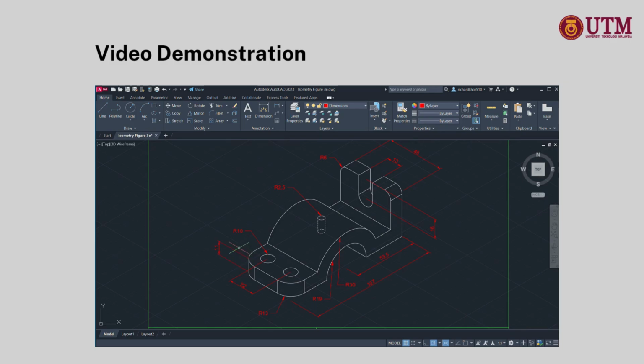And third will be figures as symbols. For example, this R10 will be a radius of 10 units for this circle, represented by the arrow. There are notes that are needed when extra explanation is required, but in this example, it is not shown. However, you can put in any sort of legend at the bottom, just in case you need to make things clearer.